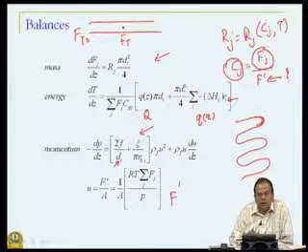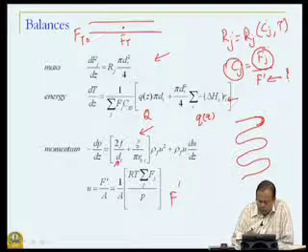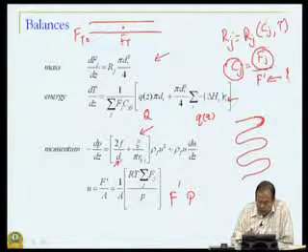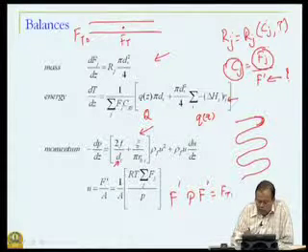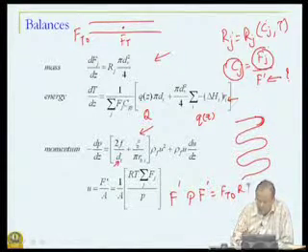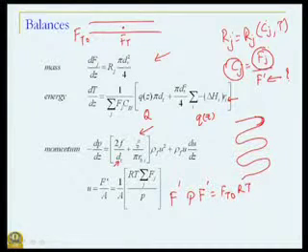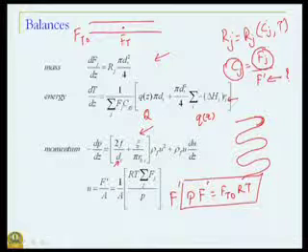And now, how do we get our flow rate F prime? We use our ideal gas law. For example, if you assume this as an ideal gas, then the total pressure into F prime is F_T0 R T, a version of an ideal gas law for a flow reactor, where instead of volume you have the volumetric flow rate, instead of moles you have the molar flow rate.